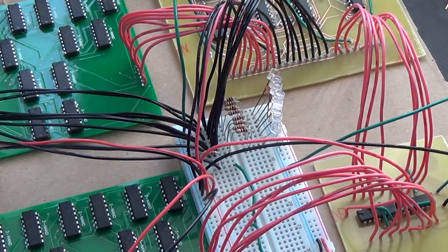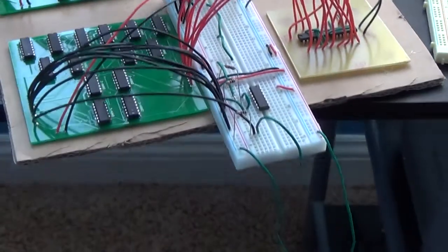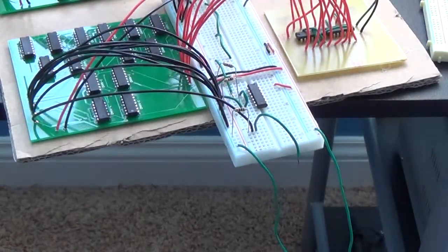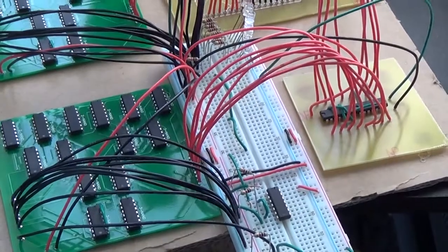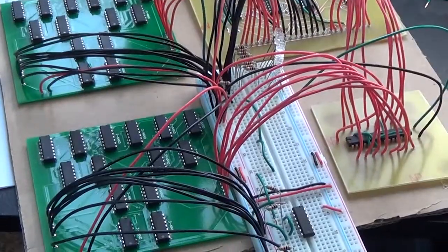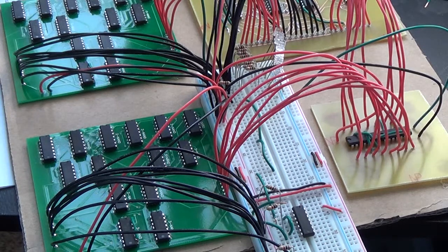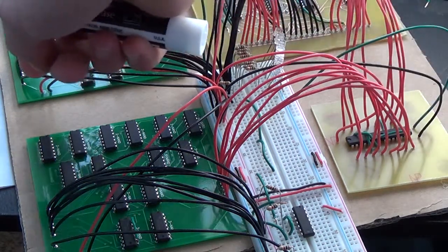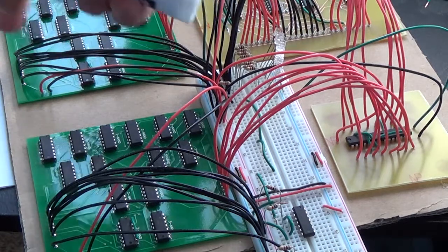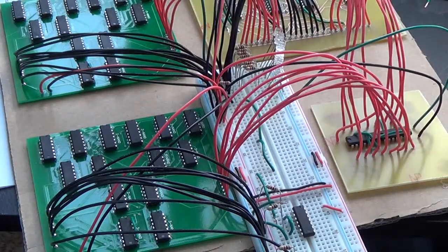So there was one problem I encountered while testing this, and that was that I couldn't just touch two wires together. I was using wires as switches because I don't have switches. This here's the enable wire, and I couldn't just touch two wires together to bring it high. I had it pulled low with a resistor, and I was touching wires together to pulse it high.